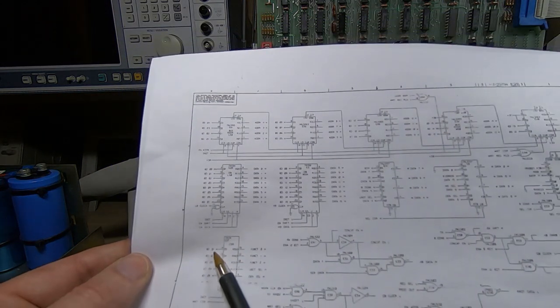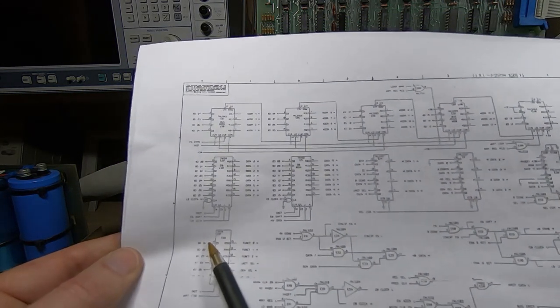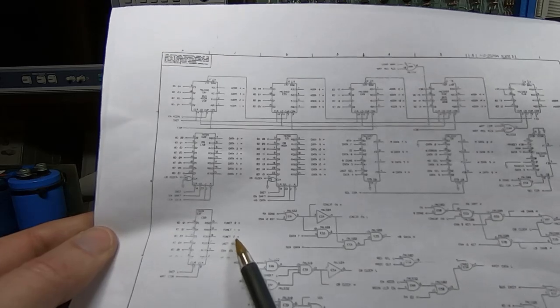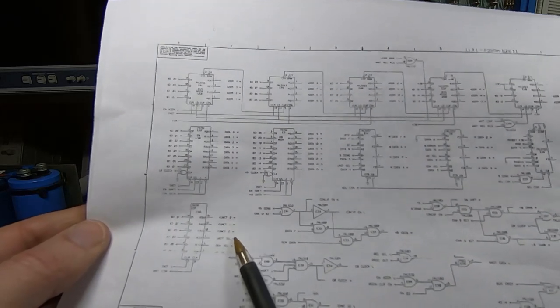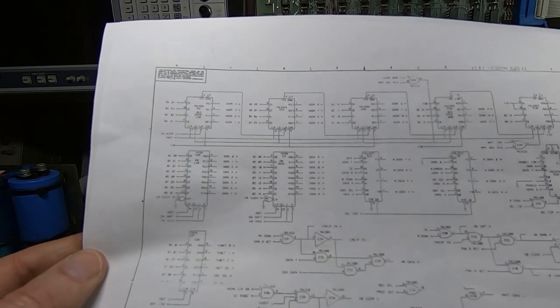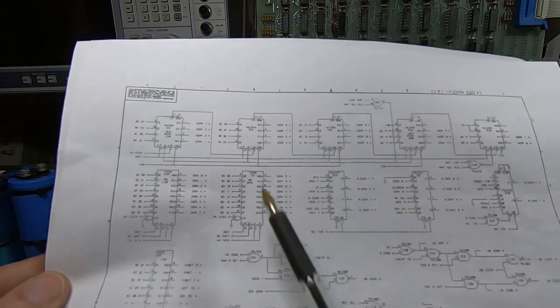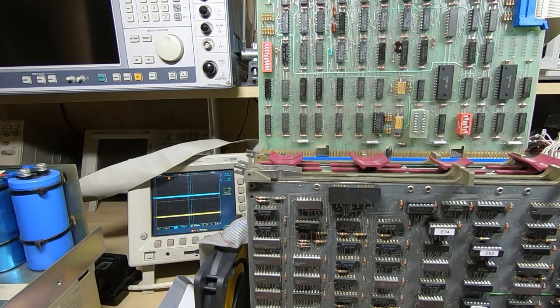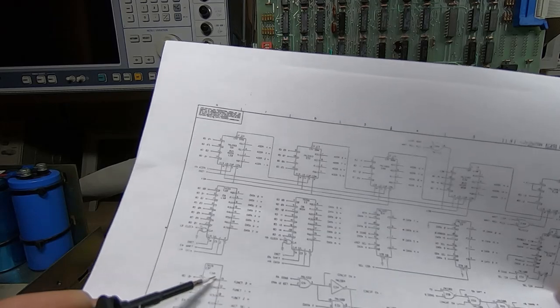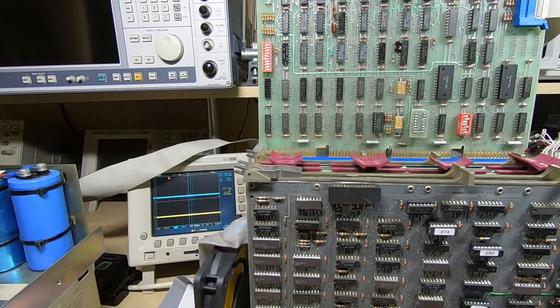And what we're looking for is that when we send the command, it comes into the input on these 3 pins, and it should set the function output pins. So we've got funct 0, 1 and 2, and all we're doing here is latching those 3 bits that we set in the command into this latch. That's the first thing, because that governs the overall operation of the interface. The pins we're interested in are pins 10, 12 and 15, and they should change in response to me sending commands through to the board. So we'll reset again just to make sure they're all clear, and then we'll check that they're all clear.